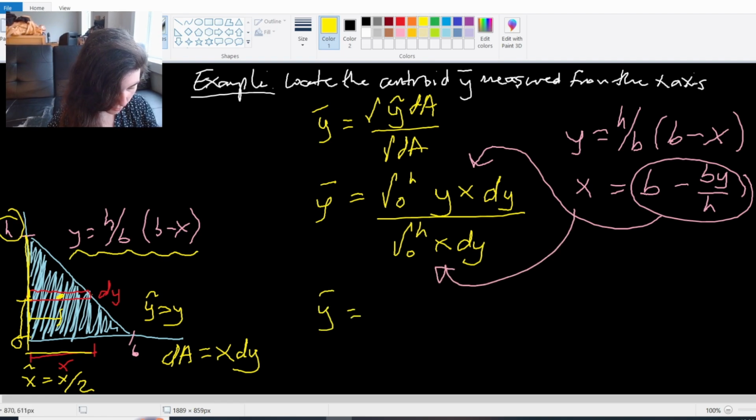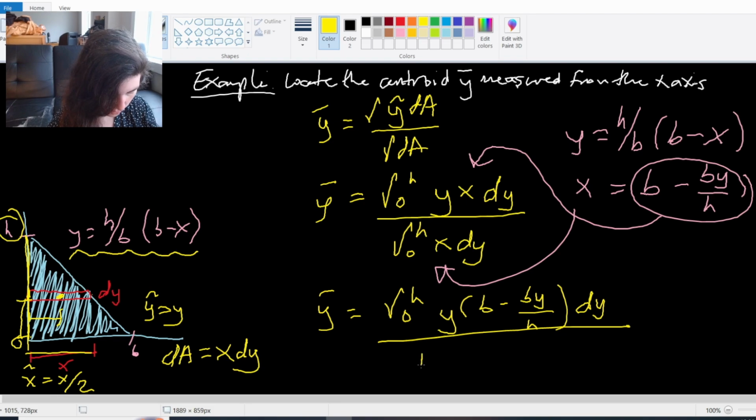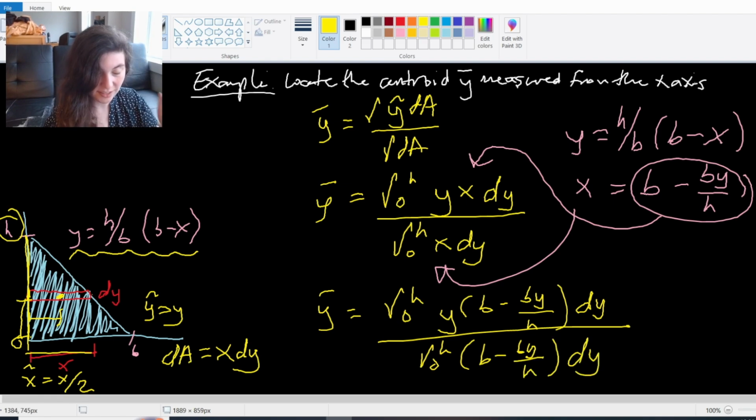Right, so my y bar full equation now is the integral from 0 to h, y times (b minus by over h) dy, all over the integral from 0 to h, (b minus by over h) dy. And that's my full integral. It's not the best looking integral we've ever seen. I'm going to have to multiply some things out to actually evaluate this thing. But I'll evaluate the top and the bottom. And when I do that integral, I get...